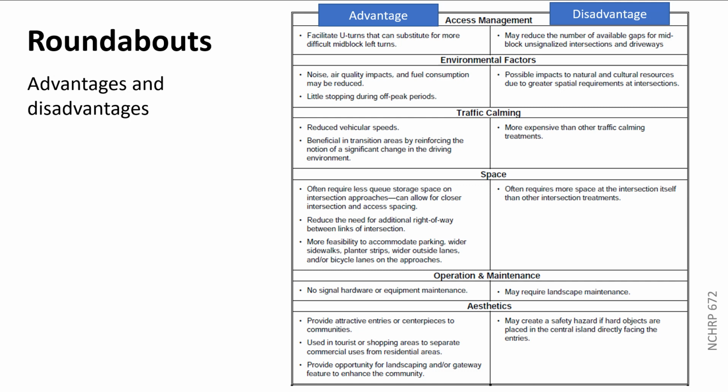They used to say the operating costs are so much cheaper on a roundabout because you don't have electricity running all the time. Well, a standard traffic signal uses between $20 and $30 a month in electricity. You're not going to save that much with a roundabout. You definitely aren't. And not only that, as time has moved on, we've decided that almost all roundabouts need to be lighted at night, with street lighting so you can see them well and they're very conspicuous. Even big state highway rural ones have tons of street lights out there. Way more power is being used there than running a traffic signal. So don't believe that. That's an old story.